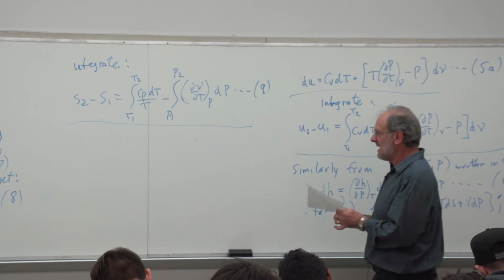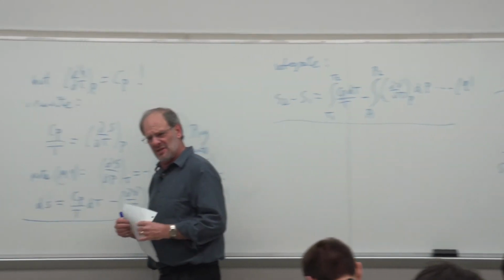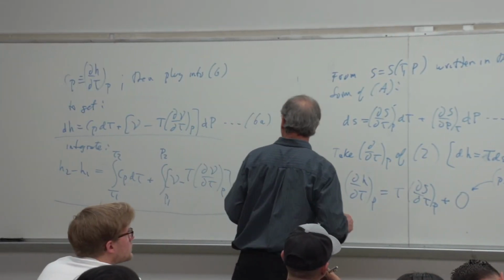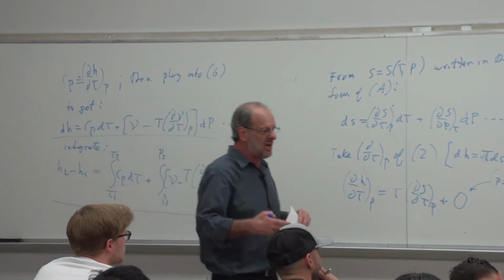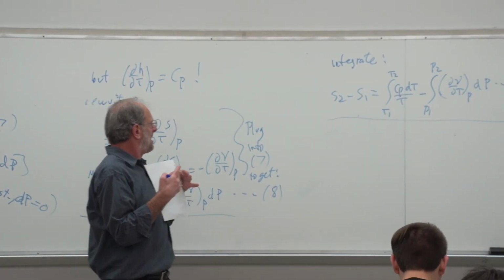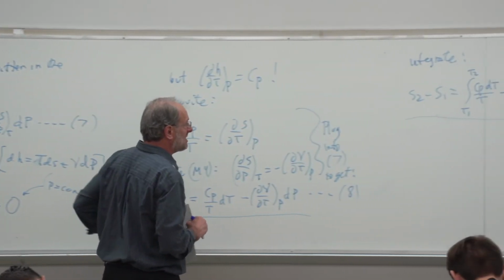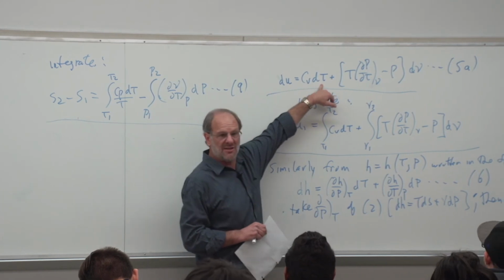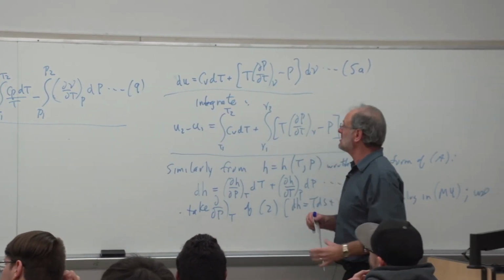So here's the equation that we're looking for, and I'm going to call this one equation 9. Now, I might note that there should be some elements of these previous equations that look familiar to you. For instance, we think about ideal gases, and eventually I will specifically talk about ideal gases. All these equations are just general, but if we have an ideal gas and we're trying to find the enthalpy change or the internal energy change, isn't dU just equal to Cv dT for an ideal gas? Yeah, that's something that we've talked about, at least in our last thermal class.